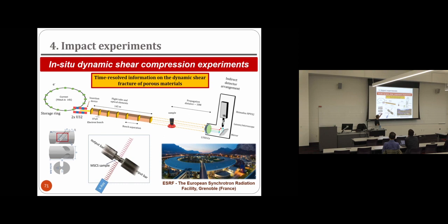Using a Hopkinson bar, because there is a Hopkinson bar there on site, we were testing this kind of sample. This I showed you before is the shear compression specimen of Rittel. So we are compressing this sample, and here we have this shear strain localization and the formation of a shear band and final shear fracture of the material.